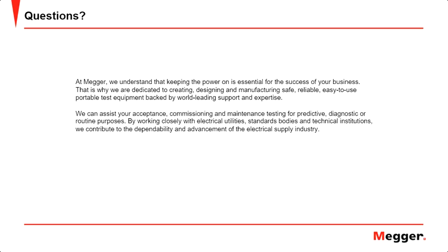Thanks, Chase. Throwing things back over to Yash. Yash, can tan delta tests be used for mixed cable types? It can, but the information that you get from it will not be very relevant. In this case, mixed cables can mask the defects of the other one. So you will have a result, but you would not be able to make much sense of it. And you cannot compare it to the IEEE 400.2 standard. So the number is pretty much useless, if you will.